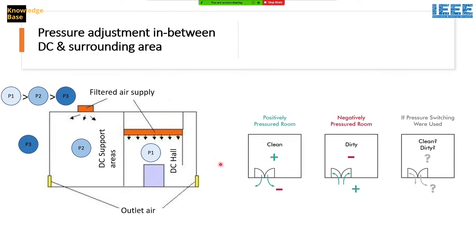And it's always required to have air circulation in the data center. So this serves two purposes. One is having air circulation in the data center, or air change, plus increasing the pressure inside the rooms, so when you come from outside, the dust or the air from inside is pushed outside, not vice versa.